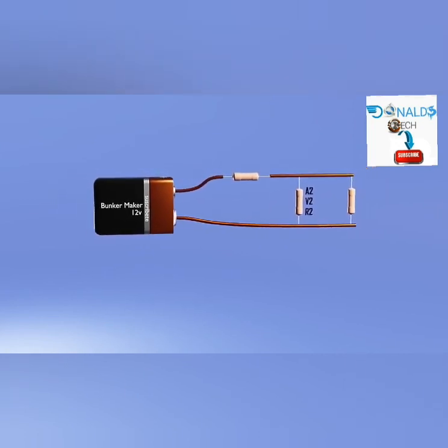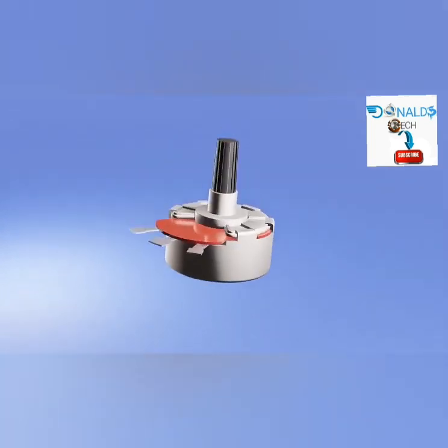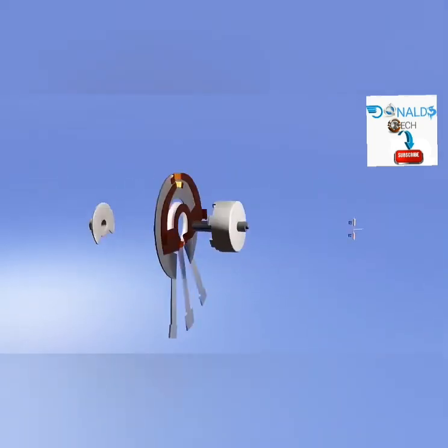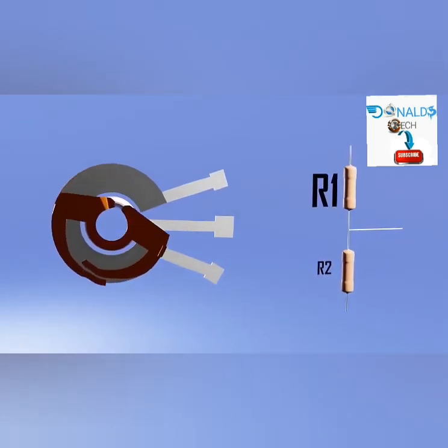As I said, a resistance allows us to control the voltage that passes through other components, and there will be times when we want to modify that voltage during the use of the circuit, not only during the design stage. And here is where the potentiometer appears. The way a potentiometer works is using an arc-shaped resistor, which, by adding a point of contact with another terminal right between its ends, acts as if it had two resistors in series.